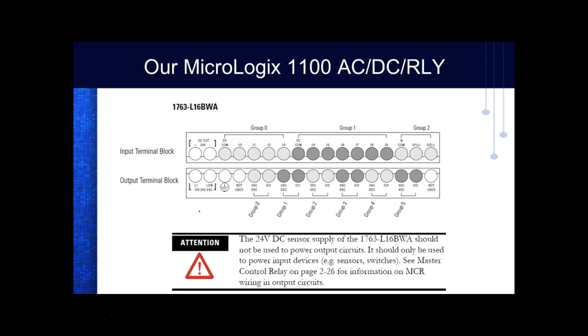So that means you've got to have a secondary power supply, right? You understand that? Your PLC DC power supply is not designed to run outputs. It's designed to run inputs. It just doesn't provide enough current. So if I wanted to make all these outputs, what's nice about this is every output is what? Either or. So you can put AC on these things. You can put DC. If you put DC, you decide if you're sinking or sourcing.